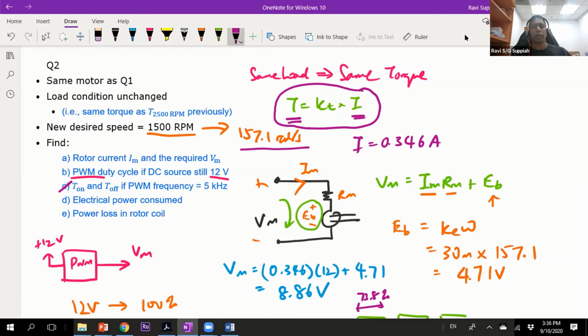Yes, you need initial torque, because you need to start from somewhere, correct? But what we are saying is when there is no load and the motor is spinning already, you reach a point where the torque is almost zero because it's just free running. So that is why we can simplify it to say that at the point when there is no load, the current is zero and the torque is also zero.